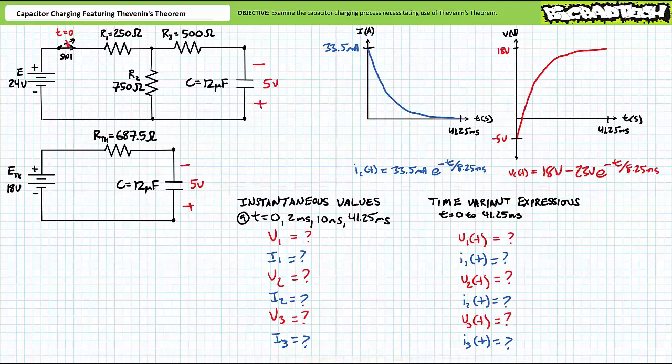If you're struggling with this bonus round exercise, here's a hint that you should not need. Make use of the previously obtained values for the capacitor at the initial, final, and specific instantaneous time states, and then use Kirchhoff's current law and Kirchhoff's voltage law to determine how current flows through the original series parallel circuit and how voltage would be distributed within it at specific points in time. You are on your own now, Guppy. These series parallel analysis skills are well within your reach. Good luck. I'll try to place the answers to the bonus round challenge in the information section associated with this lecture.